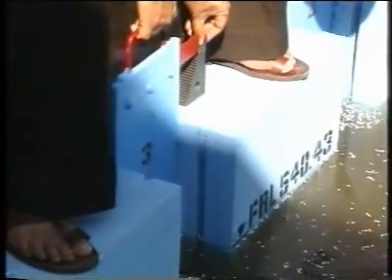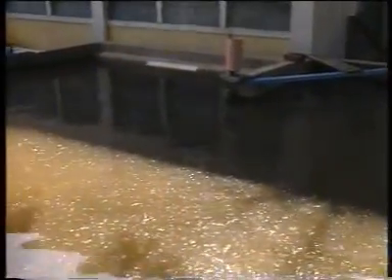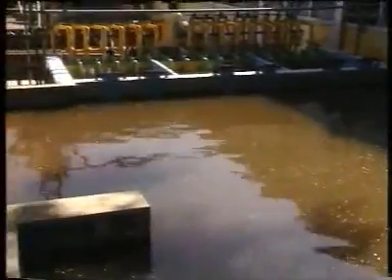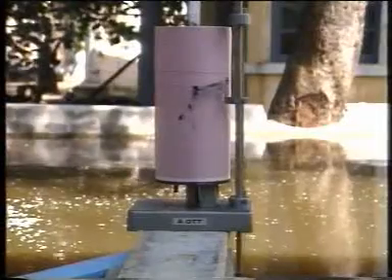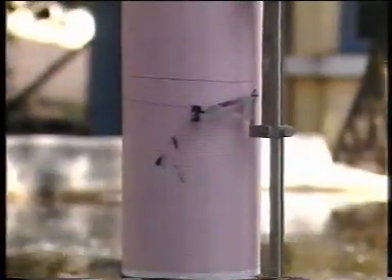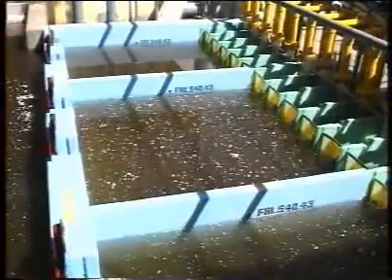The water level is maintained at FRL by using gates, inlet and outlet flow control. The approach channel water level is monitored by using a drum type floating gauge and maintained at desired constant level.